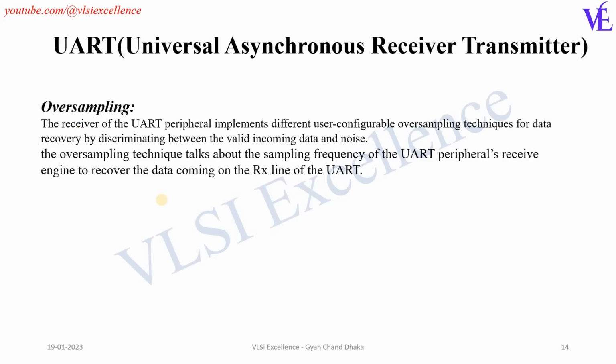Now let's understand one important concept: oversampling. As I said, the UART transmitter and receiver have to work at a specific frequency, which is the baud rate. Correct. Now I have another concept of oversampling. So what does that mean? Suppose our UART transmitter is sending data at a baud rate R. Oversampling is a concept associated with the